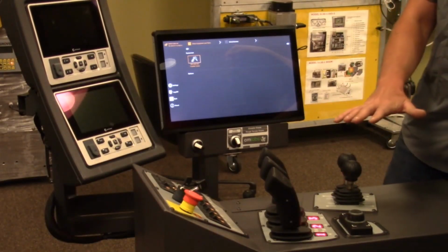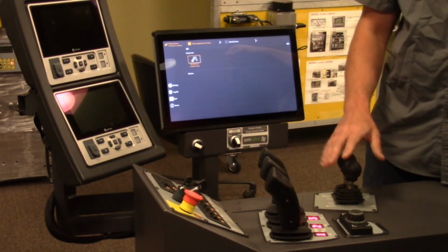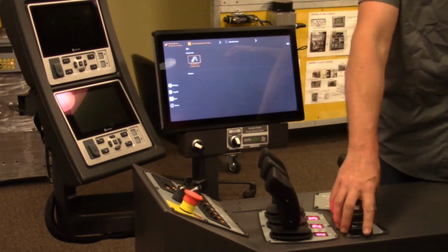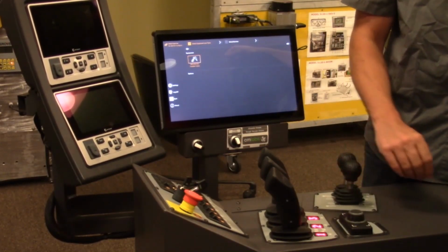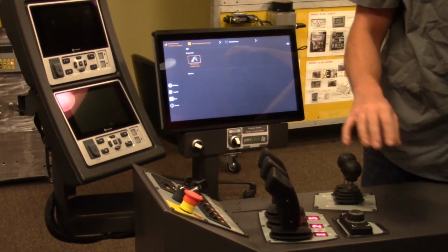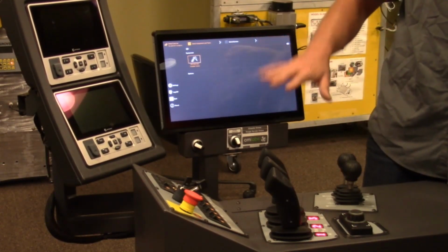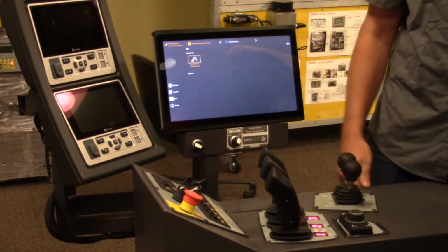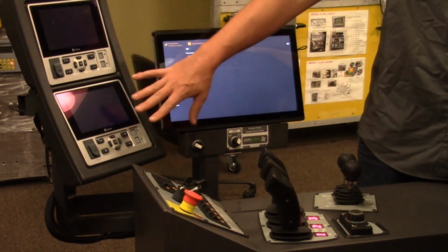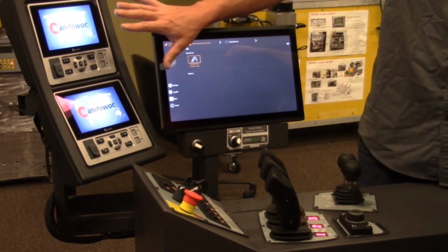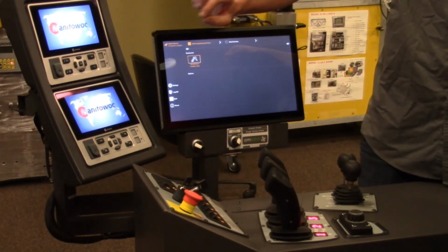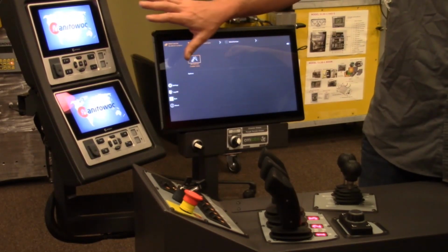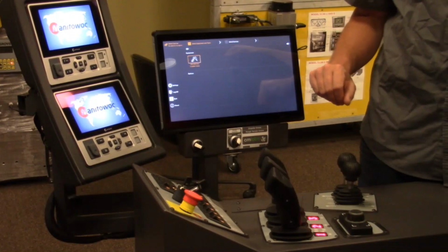So you can see here, after we've changed the crane from an RT to a crawler, we've swapped the armrest. So now we have the armrest of the crawler crane with all the CCS controls, jog dial, crawler controls. We also have the other armrest on there as well. So once the armrests have been switched, we simply change this to a crawler crane. And then what's going to happen is the RCL and ODM is going to boot up as a crawler now. So we can do the same thing. We can run through the configurations, set the crane up however we want to configure it, and run through different scenarios with the crawler crane as well.